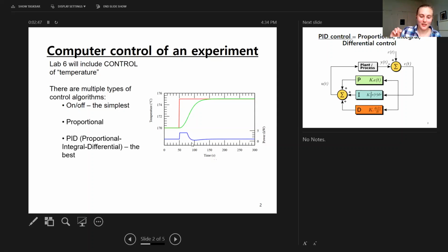I don't know if any of you guys are big Elon Musk fans, but we can talk about that another time. But he said that they used their PID control so that, since they were way behind schedule making the Tesla 3s, the ramp up time would be really fast, so they would reach the temperature, but they would overshoot and oscillate. And he's like, I bet in 2 or 3 years, all of the paint on the Tesla 3s is going to be falling off, because they didn't use a lot of control. So I thought that was an interesting story of how PID control is used in industry, and it's really applied for temperature, even just like the simple control that we would have been doing in lab.